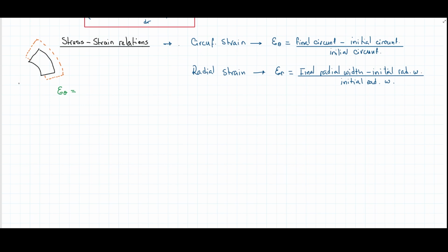And then we knew that this is the radius that we had here. So we're going to have a few important measures here. This is some sort of a deformation in the radial direction. So instead of starting at r, it's going to start at r plus u. But then in this part also, when it finishes in dr, we're going to have also a du here. Then I'm going to tell you later what's going to happen with this part here, because it's going to be affected differently, even though I draw it like that. So let me move this one from here